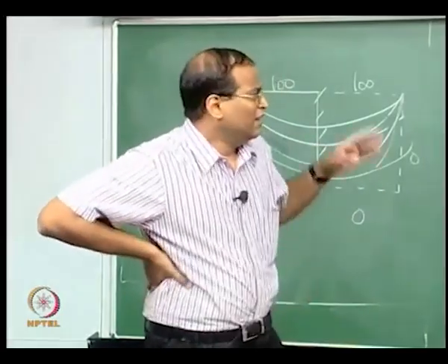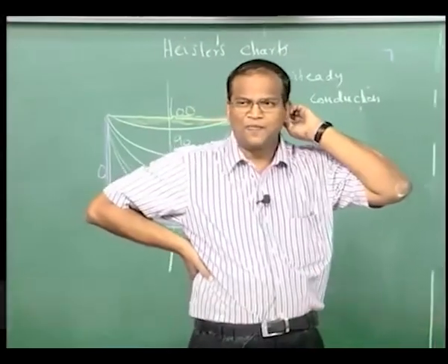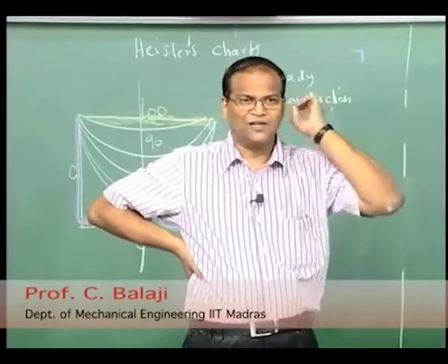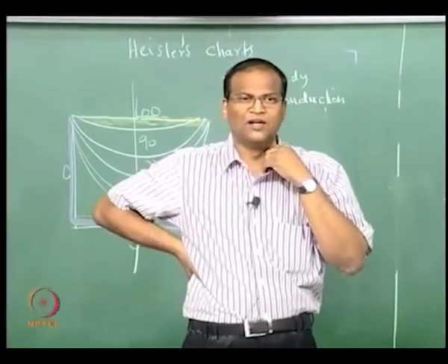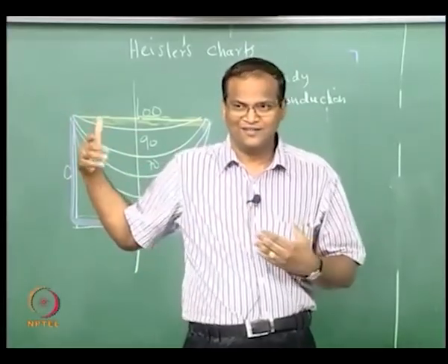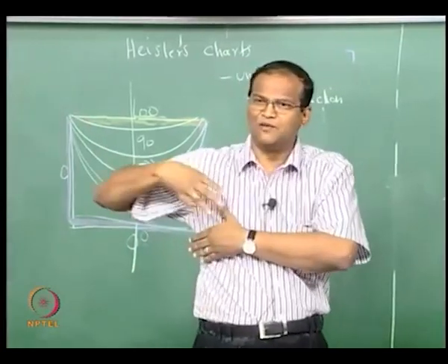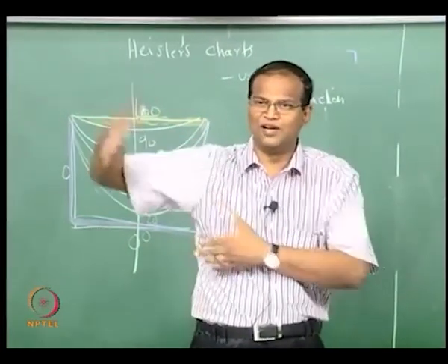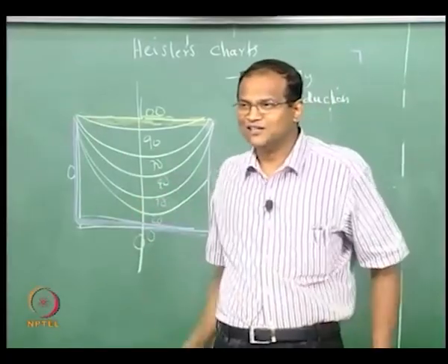Okay. This method of separation of variables can be applied to a select class of problems. Even for the cylinder and sphere, it will lead to Bessel function and Legendre polynomial, it becomes more and more involved. These are all called classic conduction heat transfer. The other is modern conduction heat transfer, we can completely bypass all this and start with finite difference, finite volume, finite element, boundary element, that is a modern approach to conduction, but this is classic.